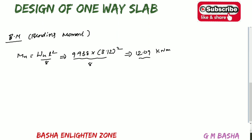Okay, after knowing this step, move to the next step, which is to check the condition. We already considered the thickness of the slab as 145 mm and effective depth equal to 120. If we take this as a trial, L by D will be equal to 25 to 30. We have to check whether this range is correct based on this condition. Therefore we are checking that.